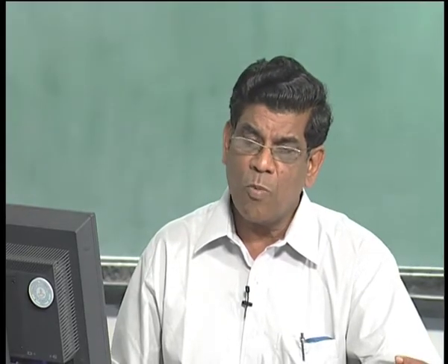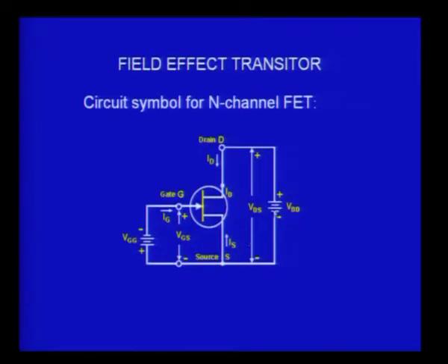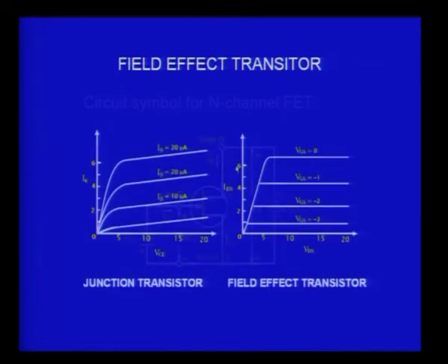And if I now put, let us say, -1 volt or -2 volts here, and then go through again from 0 to a large value for VDD, what will happen? You will see what will happen. You could have also guessed almost, you would find that when VGS is some -1 volt, the saturation will be reached even before, because there is already some negative voltage available on the gate, and therefore I have to go to a much lower voltage on the VDD supply before I can reach the pinch off condition.